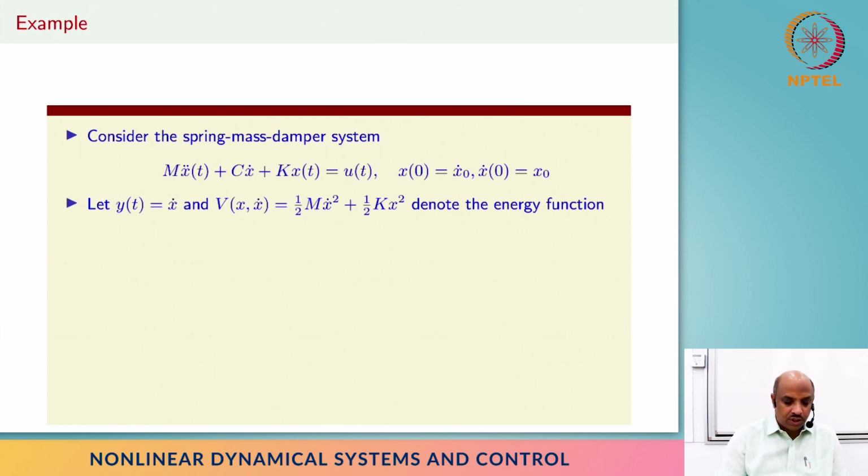We denote that by y of t, and pick our quote-unquote Lyapunov function, which is an energy function, right? But I'm going to go beyond Lyapunov stability because we have input. It's a simple exercise for you to check that when u is not there, this system is Lyapunov stable to start with, and then we can move forward and show, using LaSalle's invariance theorem, that this is an asymptotically stable system. We have probably seen some special case of this example at some point, right?